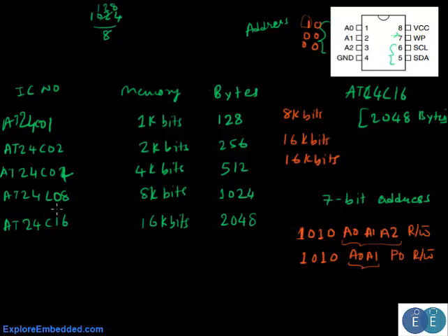And for the next, AT24C16, we cannot use these; they will be used for page addressing, and we can use only A0. It means A0 can be only 0 or 1, and we can connect only 2 such ICs. So for the 8K we will have 2 ICs which will make 16 kilobits. And when you are using AT24C16, it does not matter if you have connected these, because all the 3 bits in the address will be used for paging, and this would be read/write.